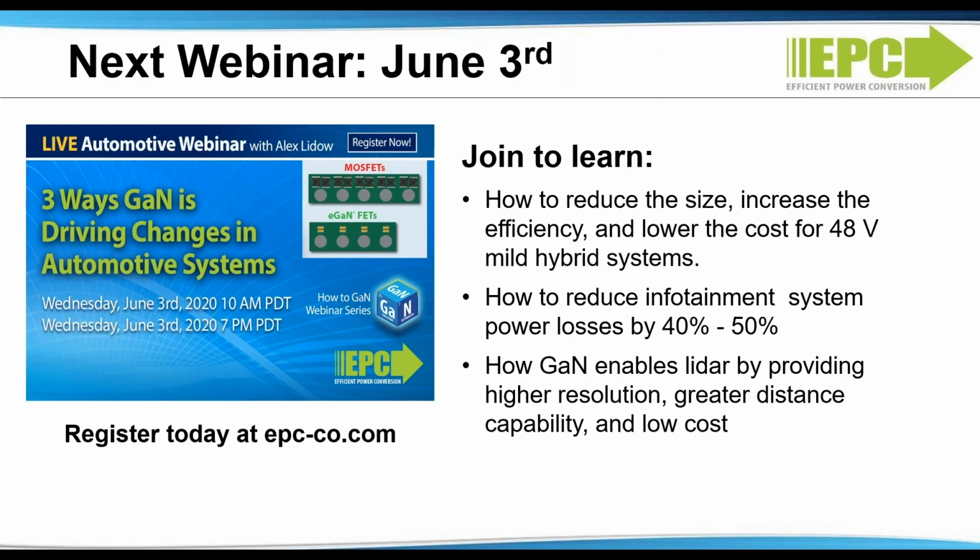The half bridge version uses half the turns and will therefore have higher current and will need larger FETs, for example the EPC2053. The full bridge will have lower current with more transformer turns, and therefore can use smaller FETs like the EPC2045. But again, your transformer has more turns, so it might have a greater DCR in that case.